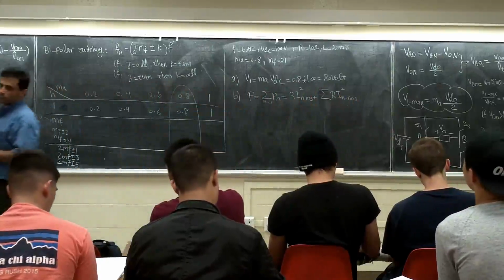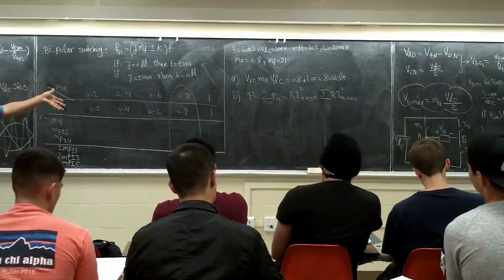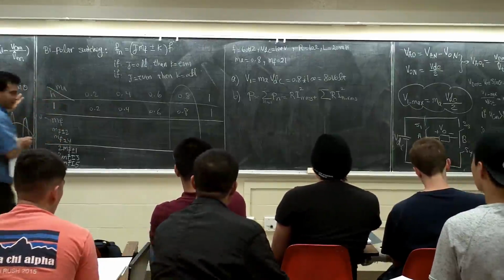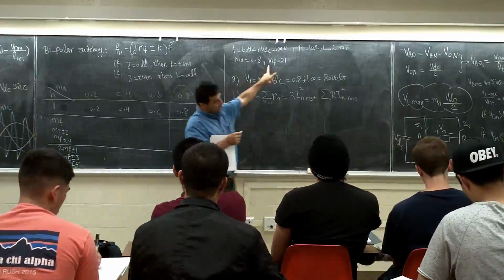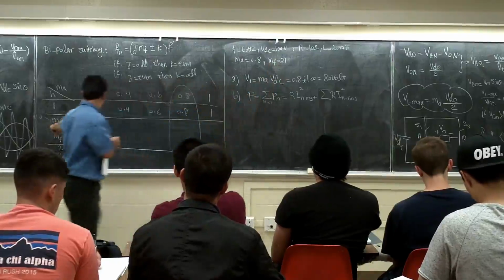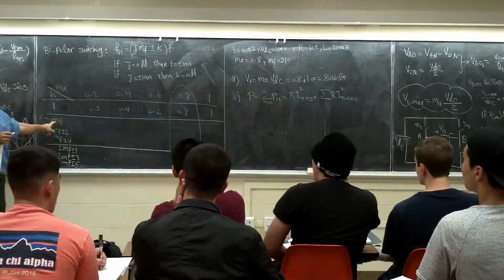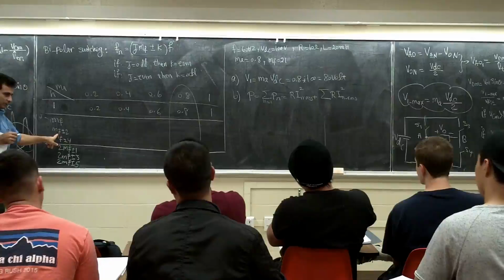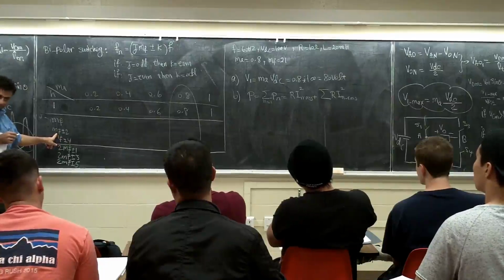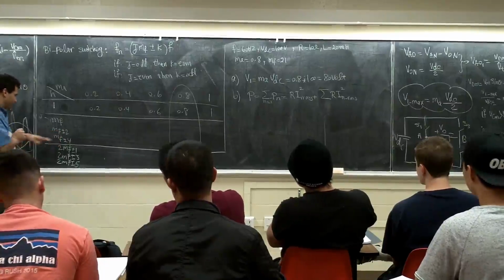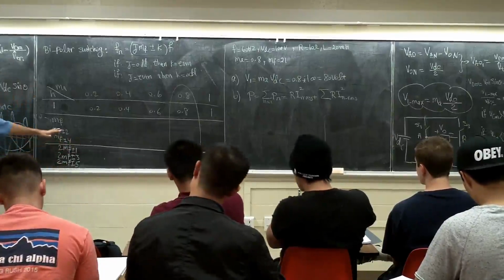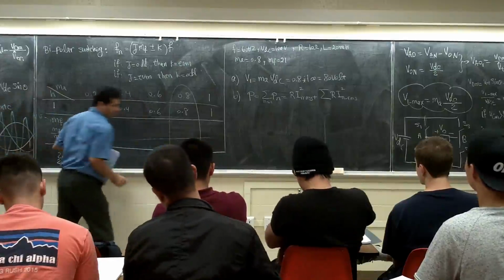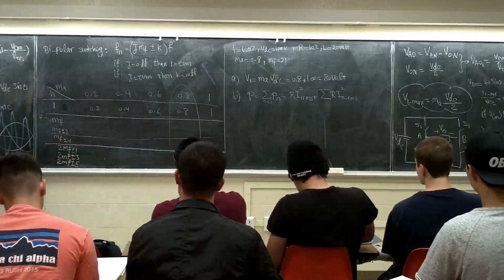So what should we do to calculate the power absorbed by the resistor? I should calculate I1. I don't know what the next harmonic is. Think about it. MF is 21. What's the next harmonic? 21. I should calculate V21, right? And what are the next two? 19 and 23, right? I need to calculate those. We're not going to go further than here. If you want to be more accurate, you can go all the way. We're going to use only these numbers, up to here. This is an approximation. Just let me complete this table for those two numbers.